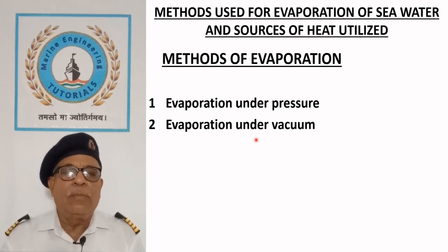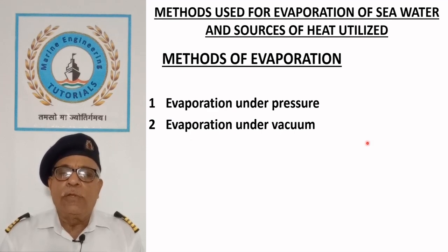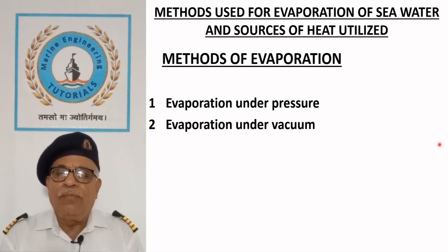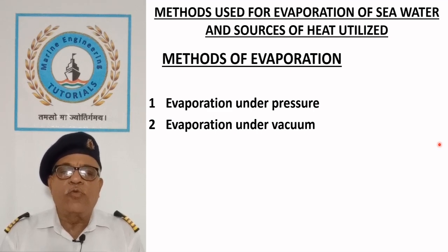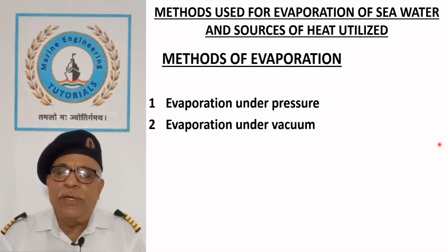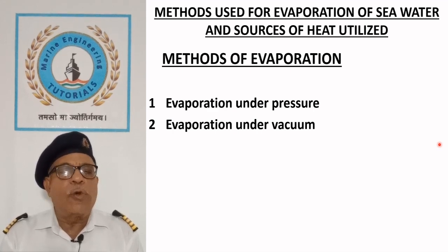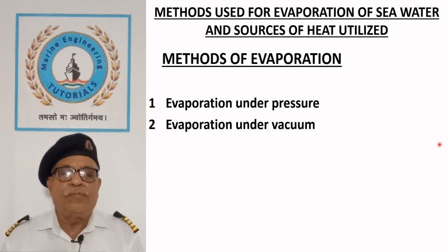Evaporation under vacuum. This method is prevalent nowadays and facilitates boiling of seawater at temperature between 40 to 50 degrees centigrade and reduces the scale formation, improves heat transfer due to high temperature difference, permits the use of waste heat from diesel engine cooling water, but requires disinfection when used for drinking purpose.